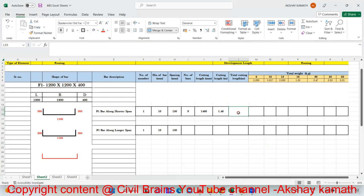Now come to the total cutting length. Total cutting length is very important. This 1.46 cutting length is for a single bar. So what will be your total cutting length? It will be the cutting length of one bar multiplied by the number of bars. Number of bars is 9. This will give me the total cutting length of the entire F1 footing along the shorter span only. But how many such footings are there? We know only one footing is there. Then 1.46 into 9 into 1 gives the total cutting length in one F1 footing along the shorter span.